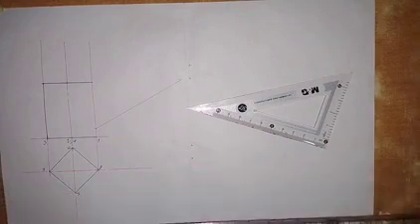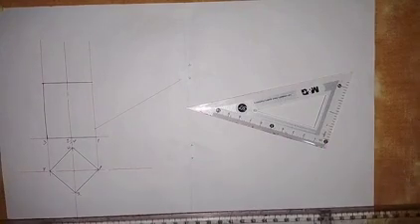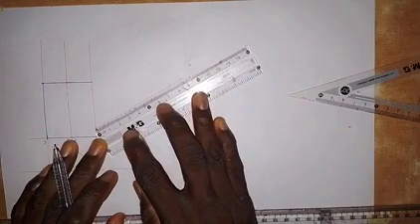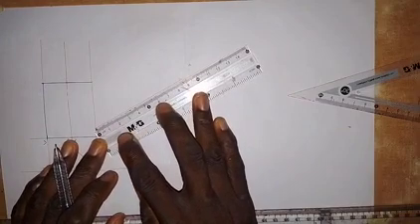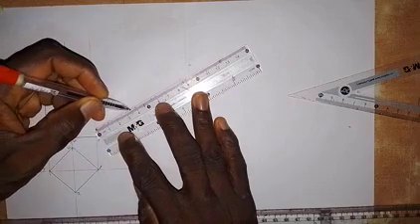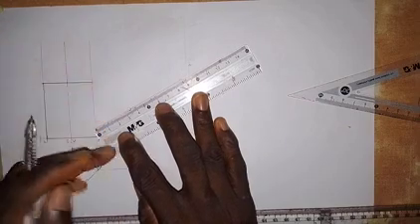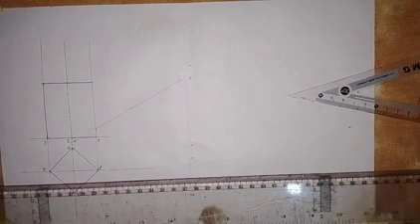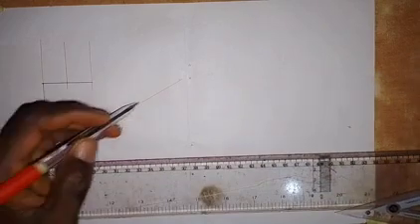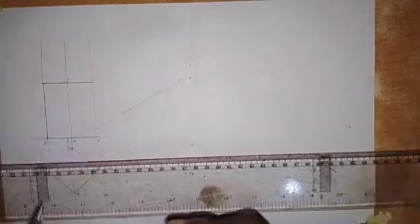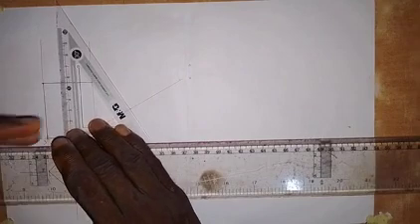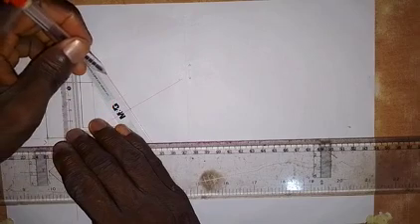Then having drawn that line, the next thing I'm going to do is take a measurement of 35 millimeters. I'm trying to make sure that you understand this construction. So this is 35 millimeters here. Then with this 35 millimeters that I have taken, since I have drawn this line at an angle of 30 degrees to the horizontal, I will take the 60 degree side of the set square and draw a perpendicular line to this line. That's a line that will be at a right angle to this. So we have this line.